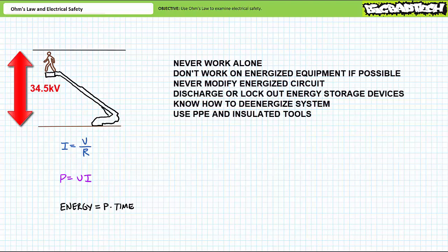Here are some general safe work practices you should follow in working with electricity. Never work alone. If your team is working remotely, stay in contact with your operations and maintenance organization using radios. Turn the power off. Certain measurements must be made with the power on, but if at all possible, turn it off when connecting instrumentation, then turn it back on to make the measurement. Never modify a circuit with the power running. You could accidentally short circuit critical current controlling elements. This is especially important when incorporating ammeters into a system.